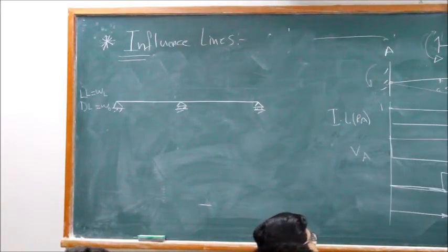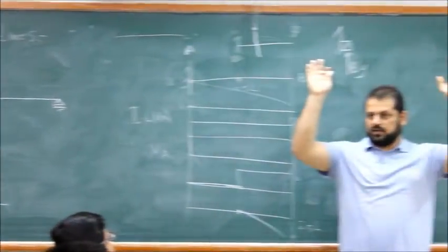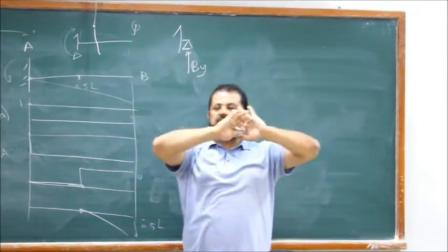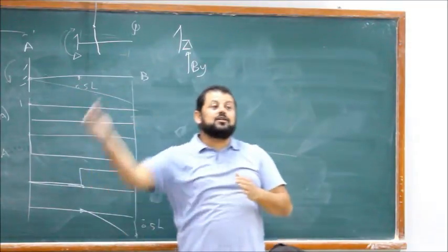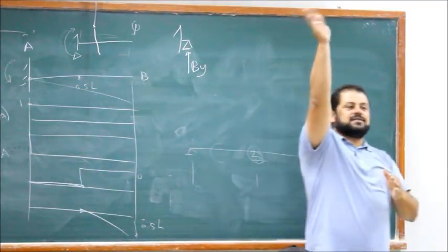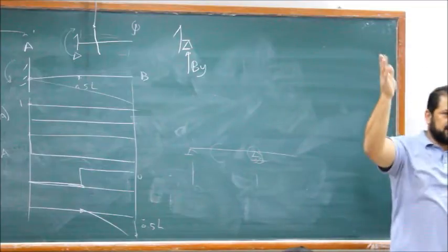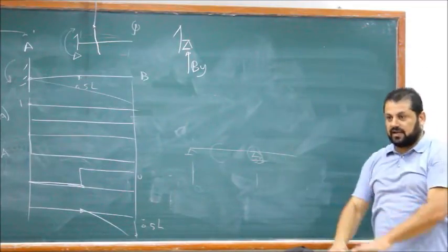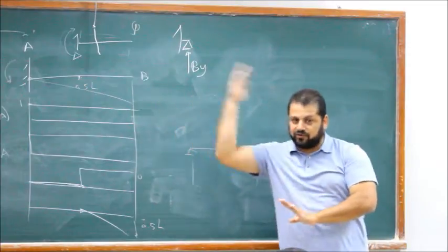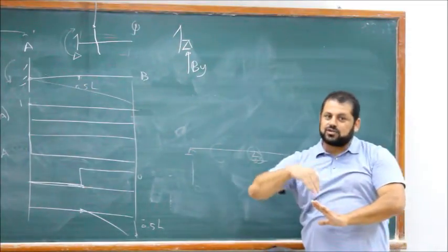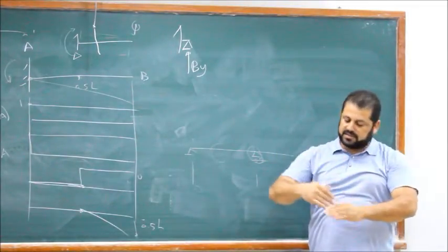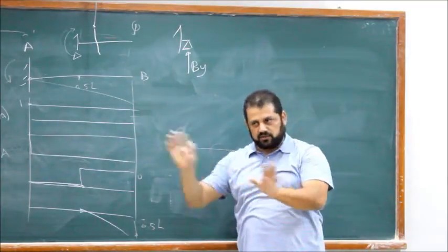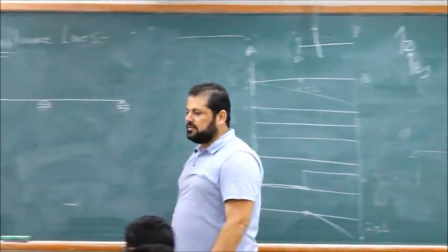the self weight of the structure, which is everything. We built the frames, the slab, and everything. This is when you build the structure, the main skeleton. That's the self weight. There is additional dead load: tiles, ceilings, mechanical, electrical. It's dead load. It will stay there, but it is added after you build the structure. So it's called superimposed dead load. Even in the software, the dead load is the self weight plus superimposed dead load. They are dead loads.